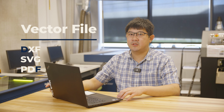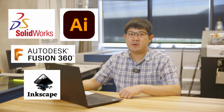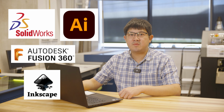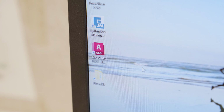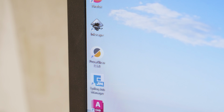So, to start your first laser cutting project, you're going to need a vector file, such as a DXF, SVG, or PDF. That can be generated from a large range of CAD or 2D vector software. One app that's particularly helpful in creating and manipulating vector designs is Inkscape. We have a general video tutorial linked above if you're unfamiliar with it. We also have Illustrator, AutoCAD, and several other similar applications installed on our laser cutting computers. However, sticking with the same program used to design the file is usually best.